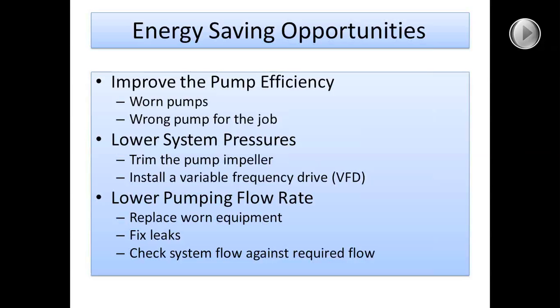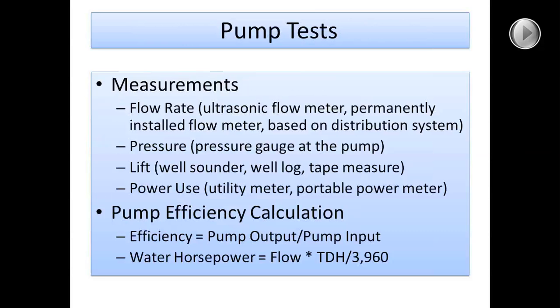Pump tests. We do pump tests, and I don't expect that you will all be doing pump tests. We'll just be collecting what information we can out in the field. But a lot of times, my group will do pump tests. We'll go out there and measure the pumping flow rate. This gives us the best information we can possibly get on a pump. We can calculate the actual real pump efficiency. So I thought it would be good to cover that today.